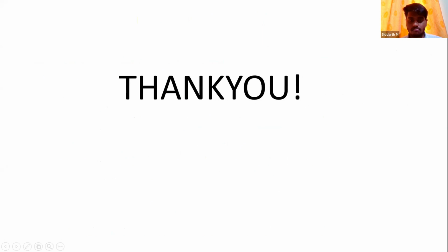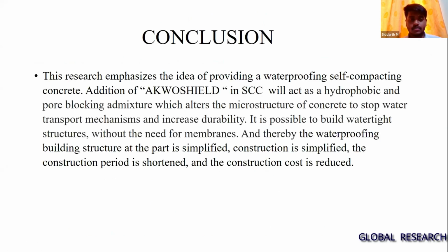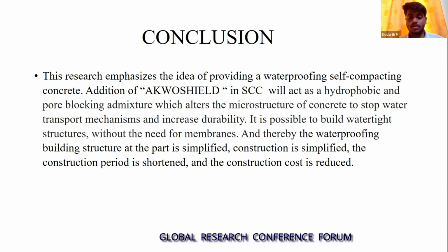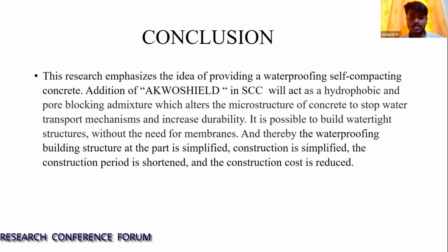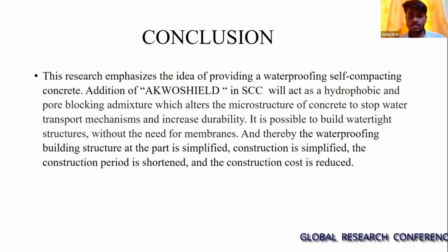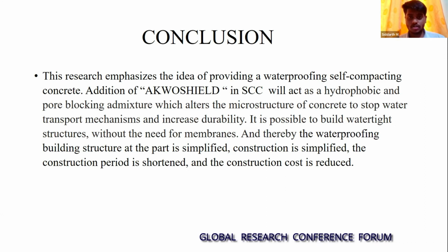So lastly, the conclusion is that this research emphasizes the idea of providing waterproofing self-compacting concrete. Addition of AquaShield in SCC will act as a hydrophobic and pore blocking admixture which alters the microstructure of the concrete to stop water transport mechanisms and increase durability.